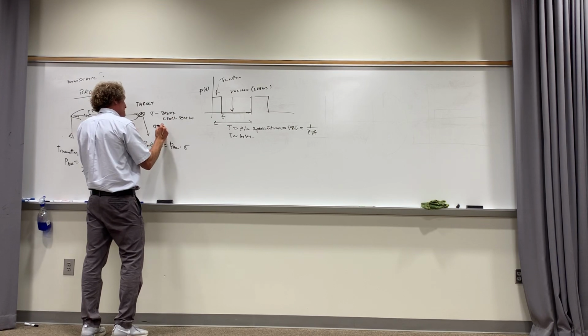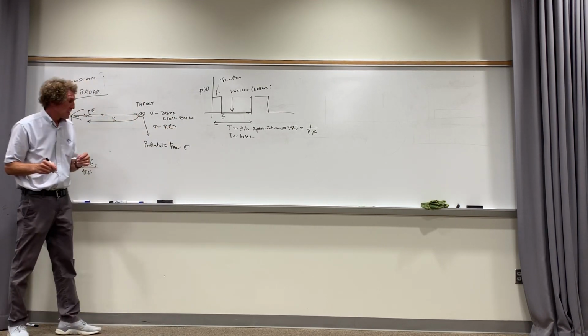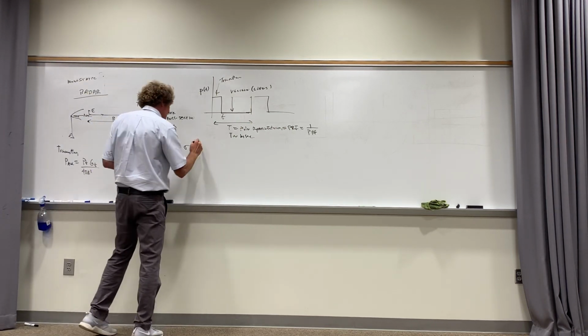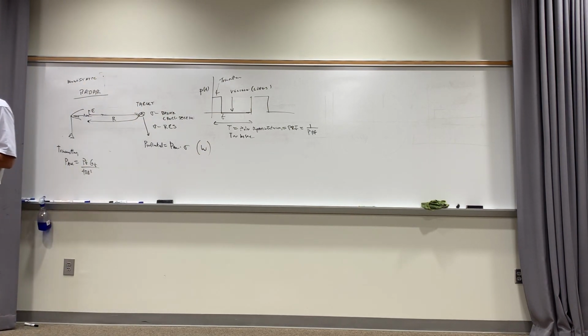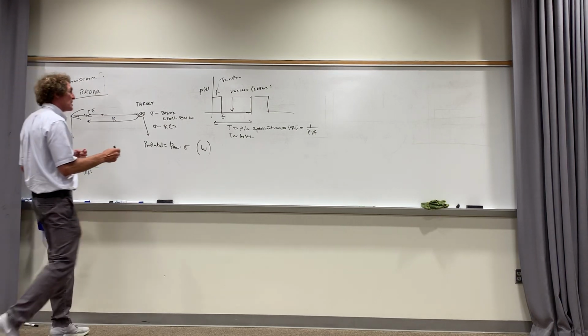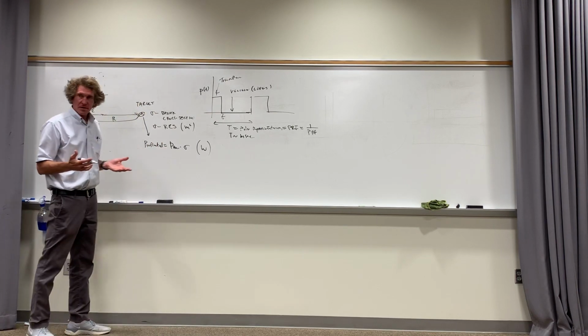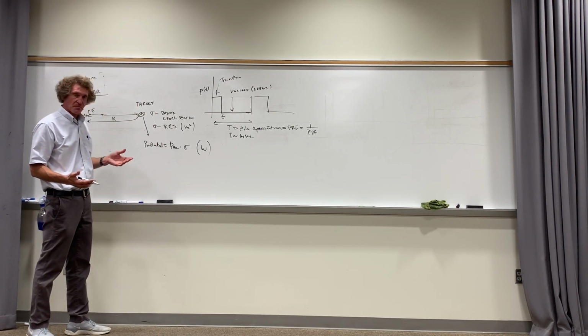And sigma is often termed the RCS, radar cross section of a target. So this is the total amount of power reflected, and it is in watts. Please make sure you write that down. And that should make sense to you. If you have a power density of so many watts per meter squared, and it hits something with a certain RCS, and our radar cross section is in meters squared, better put that down, this is in meters squared, then what results is watts, right? Watts per meter squared times meter squared is watts.